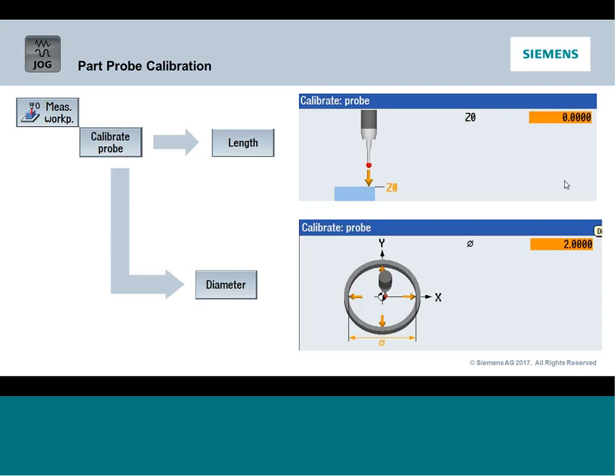Now, the ring gauge has to be mounted to the machine. It can't have the potential of moving. Obviously, we're going to start to move around and touch a couple sides, so we don't just want it sitting there. You could use a strap clamp to hold it down to the table. Sometimes we butt them up against a mag base. There's not a lot of pressure on these switches. Probably there's more force induced by the table moving around than anything else. So you just want to make sure the ring gauge is sitting fixed on the table.